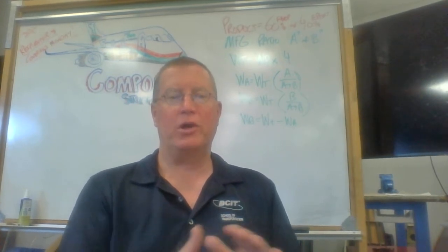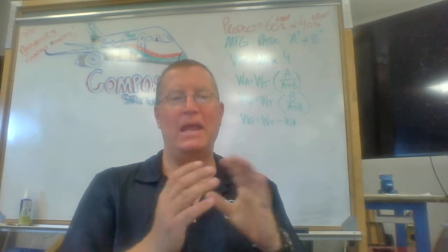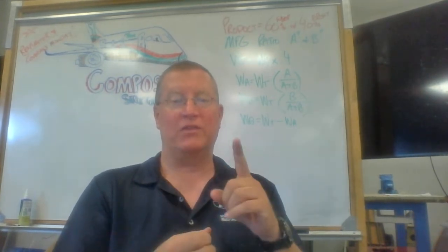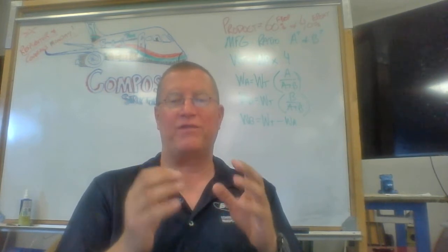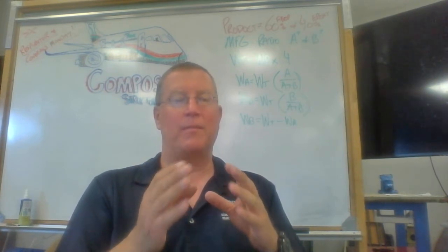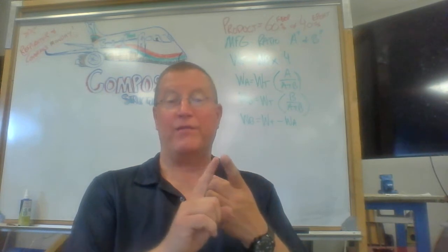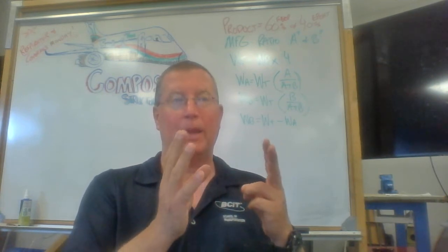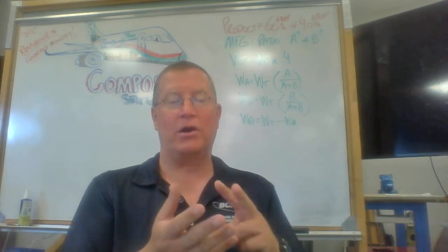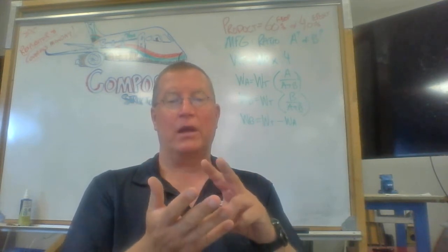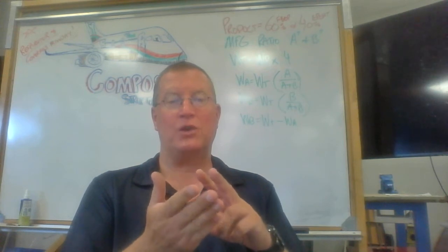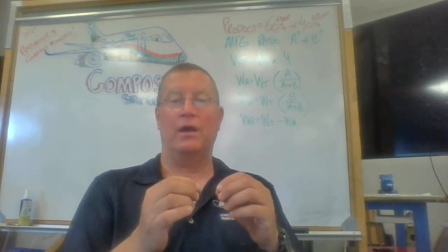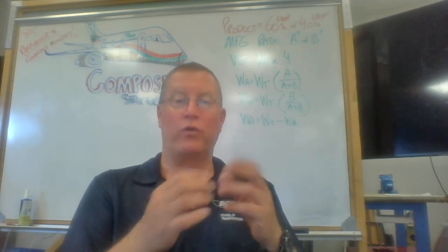And so the prepreg, the main reason why within aviation we use prepreg comes down to one thing, and that one thing is the fact that the manufacturers have the ratio perfect, but they've also integrated that epoxy into the fabric at the exact perfect ratio so that we are pulling the absolute maximum performance out of that fiber for the application.